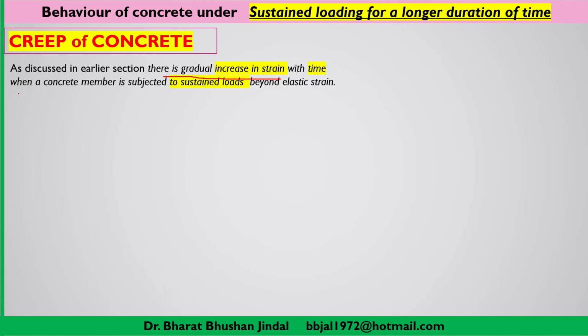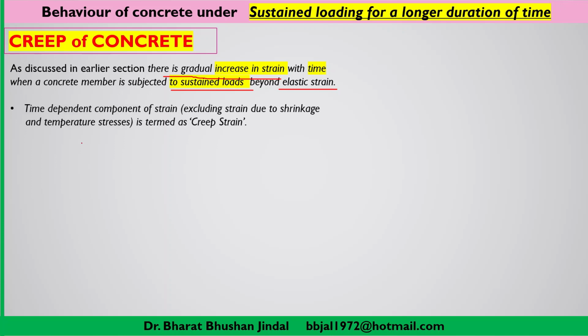So when a concrete member is subjected to sustained loads beyond elastic strain, then we can understand that another important aspect is creep strain. That means it is a time dependent component of strain.